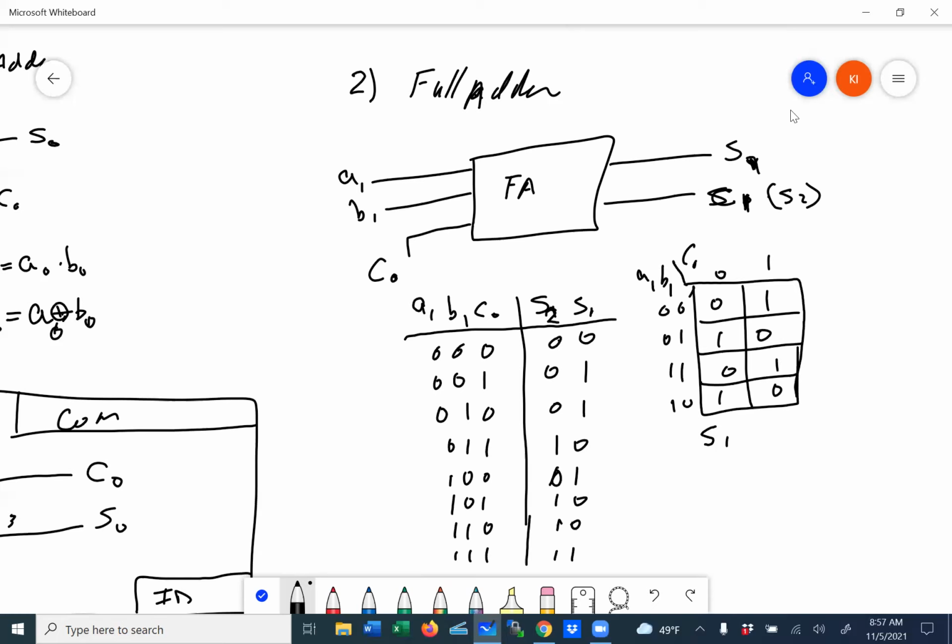Yeah. Now, this pattern, when you play with it a little bit, you can write the equation, but if you write the equation without seeing the pattern, it's going to be pretty complicated, with lots of gates, because the prime implicants are pretty small. But whenever you see a pattern where every other cell is one, that typically means what you're looking at really is an exclusive OR.